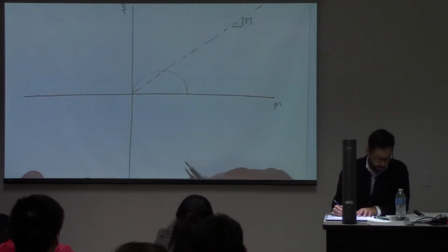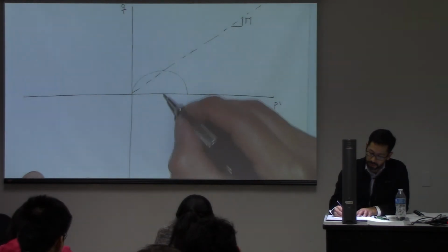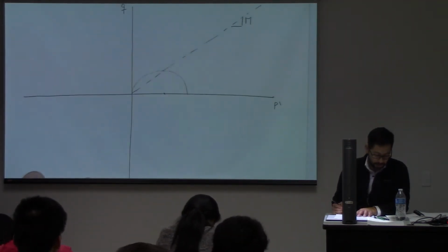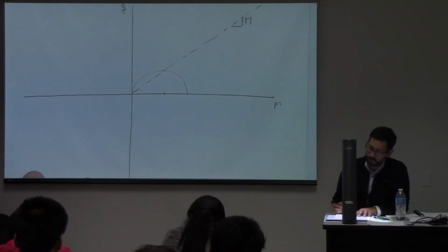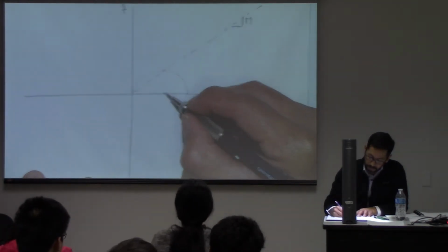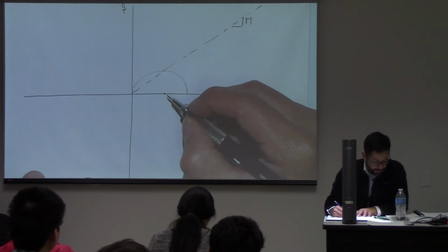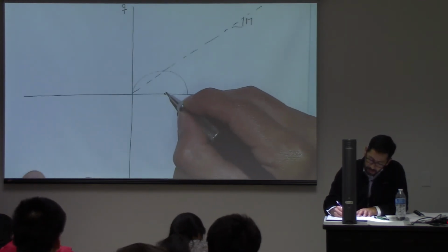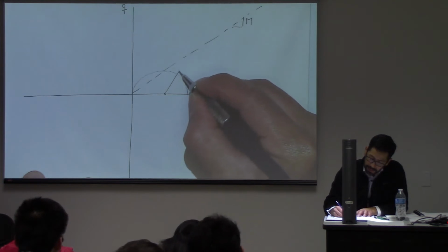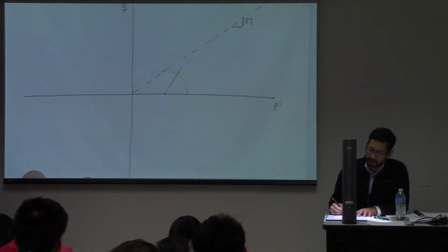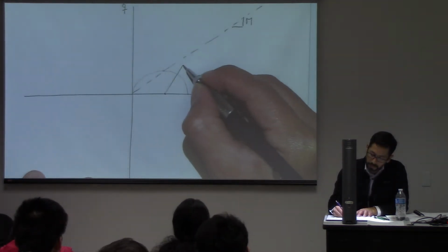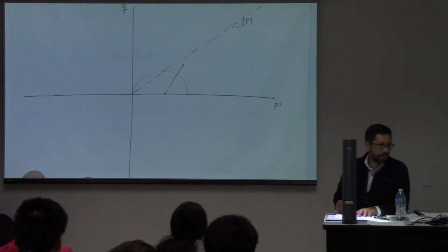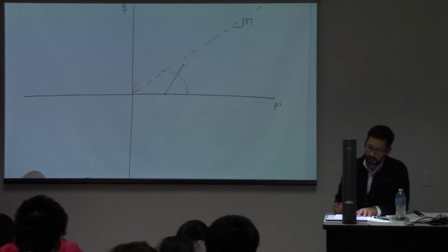So what I'm going to do now is I'm going to start somewhere over here. I'm going to do a triaxial test. So let's say that I do a triaxial test in which I increase deviatoric stress, I pass the yield cap, and I stop halfway. I don't get to the critical state line.